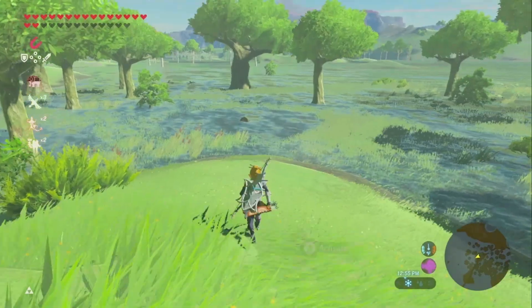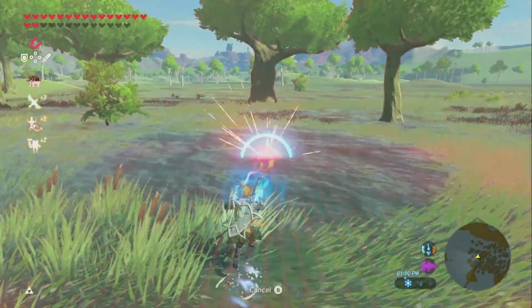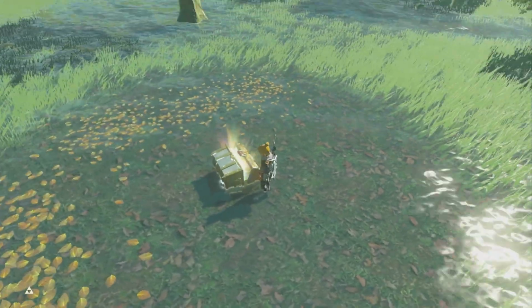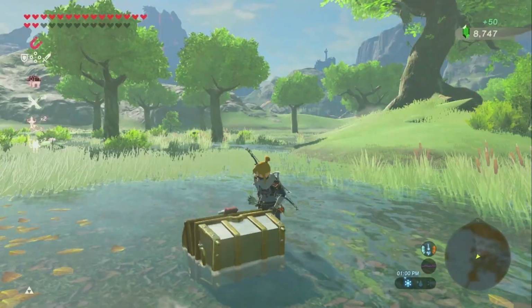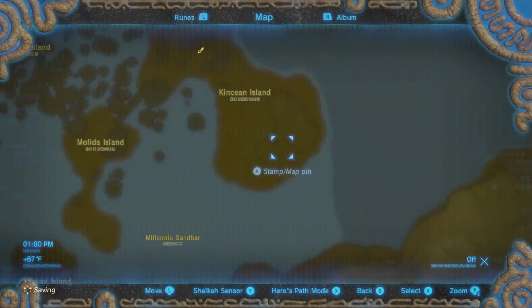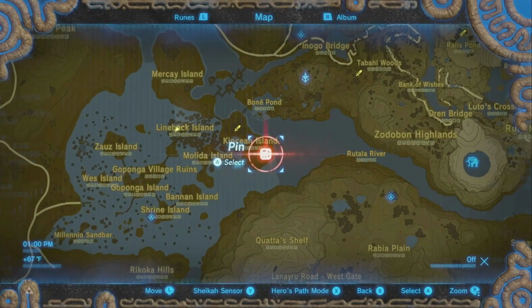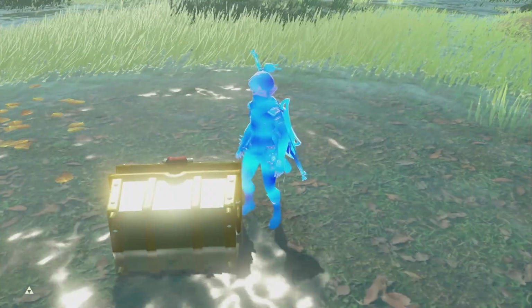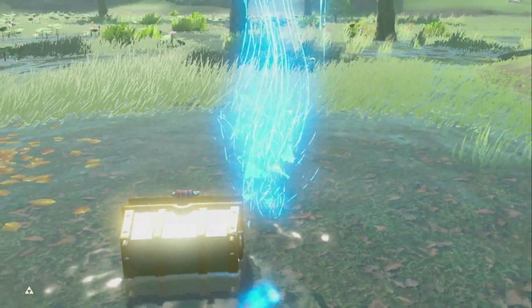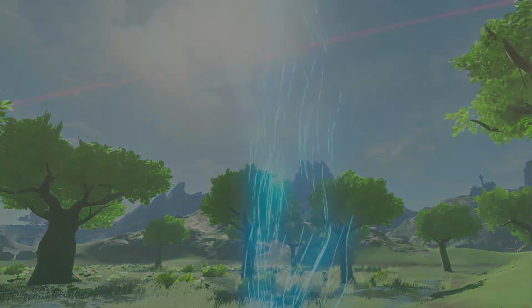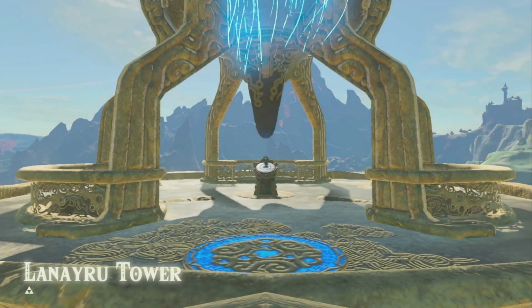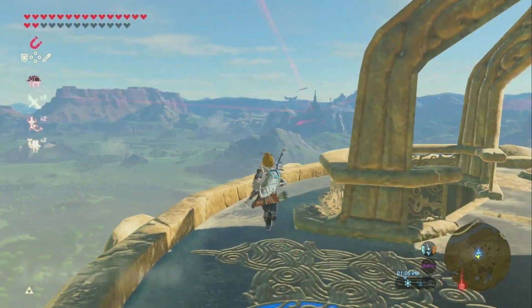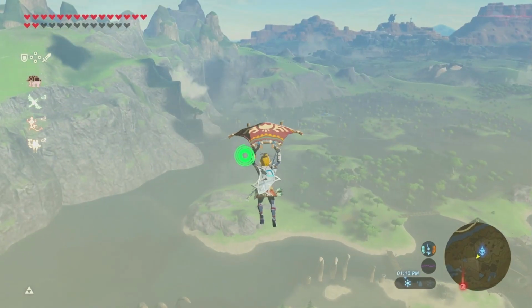6. No discharge tube. Dangerous, may scald people. 7. Discharge tube too short or diameter too small. 8. Discharge tube damaged, kinked, or split. 9. Discharge tube dripping or leaking. 10. Discharge tube capped, threaded at outlet end or rusted closed at the end. 11. Discharge tube combined with other piping such as condensate drain or other temperature/relief TPR valve.